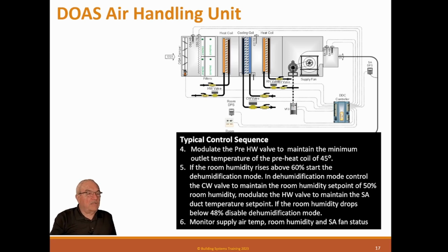Standard dehumidification sequence like the other ones. Monitor the supply air temperature, room humidity, and supply air status. So this is basically a DOAS unit.